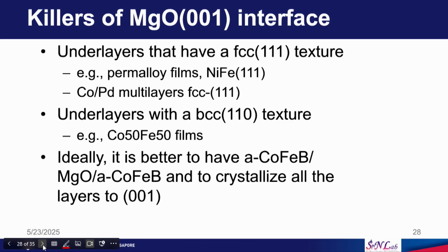As I mentioned, if you have materials with the FCC 111 texture, it is not good. So, we have to break this FCC 111 or BCC 111 texture, but we should focus on getting BCC 001 crystal structure. That is important.